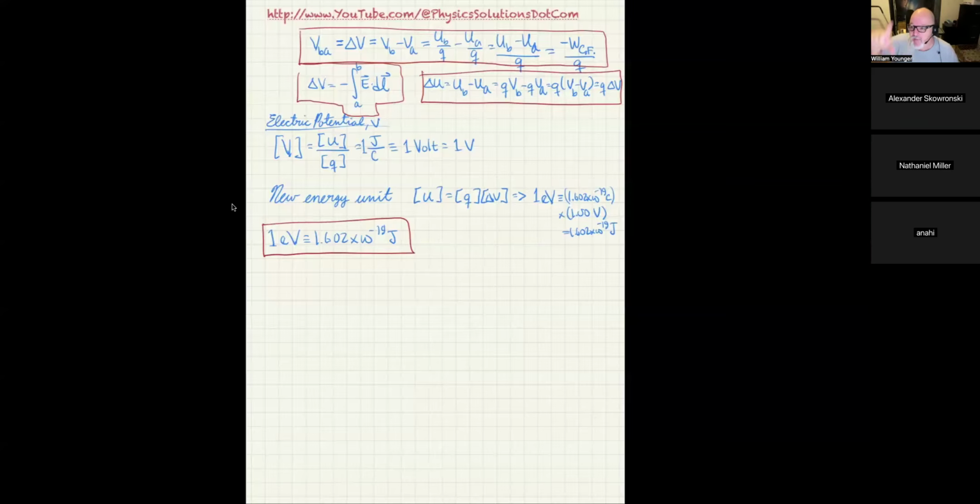It's also not the peak to peak. It's not going from positive 60 down to negative 60. That's not it either. It's actually what we call the root mean square, which you've learned a little bit about already. Basically, if you calculate the root mean square of the sinusoidal AC voltage, you'll find that it comes out to be around the 120 mark. It's basically the peak voltage divided by the square root of 2.